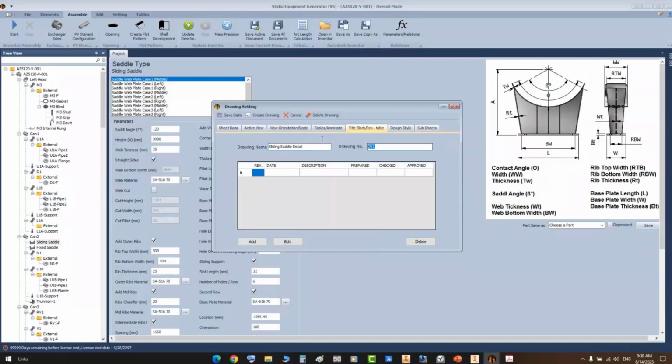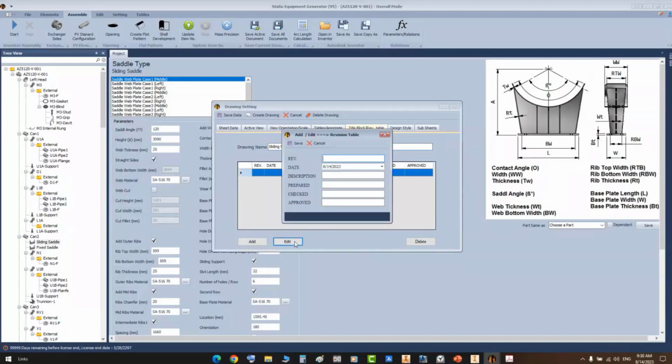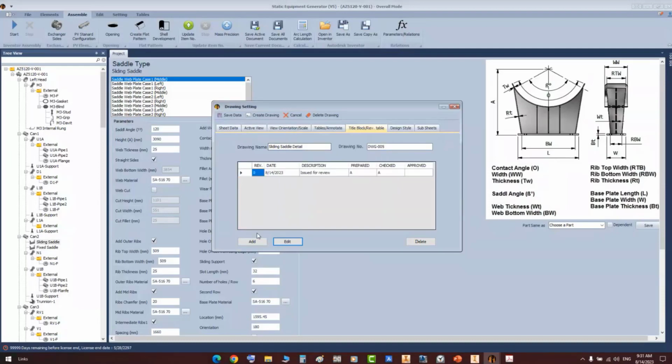Okay. And give it this drawing document number, like UG example. And from here, let's edit the revision table. It's revision 0, for review. Okay, and prepared by, checked by, for that, and click save. Now you can add some empty rows to the revision table.